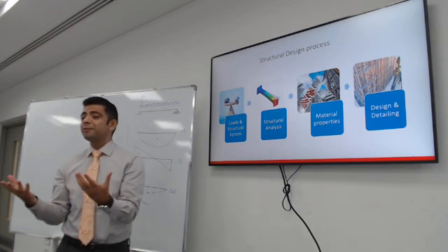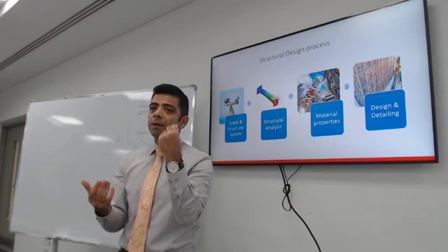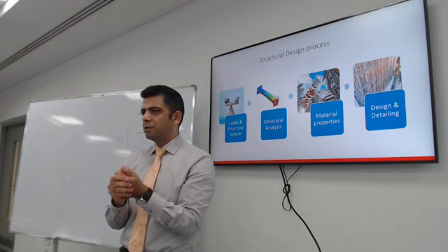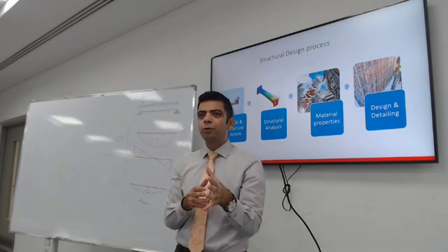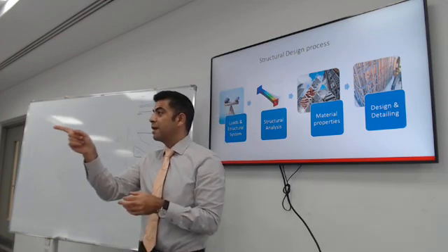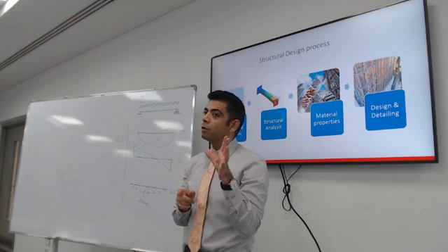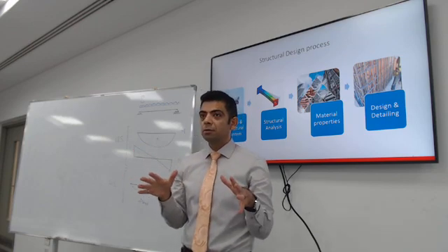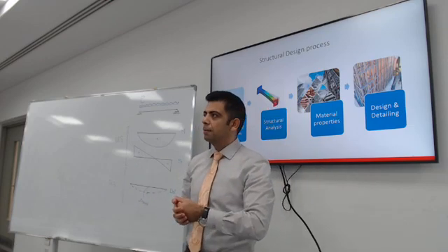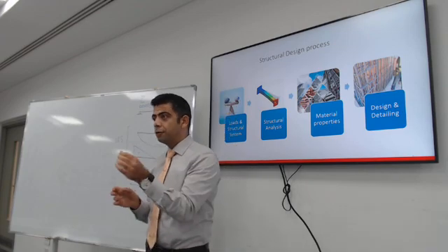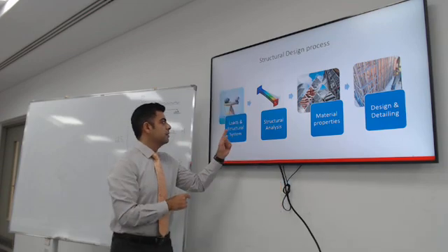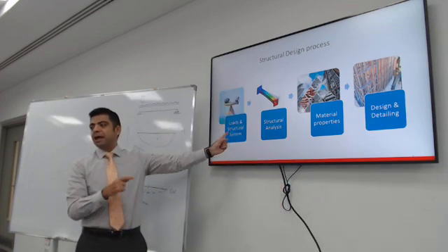Do you remember what was the first requirement in your presentation or the final coursework for the project? What was the first thing I asked you to do about the structure? Yes, that was definitely there. I was hoping someone would remember the structural layout. Was that something you did at the beginning or at the very end of the project? At the very beginning, the structural layout. I need to figure out where the columns are, where the beams are, and the walls in order to get the structural system and calculate the loads on it.